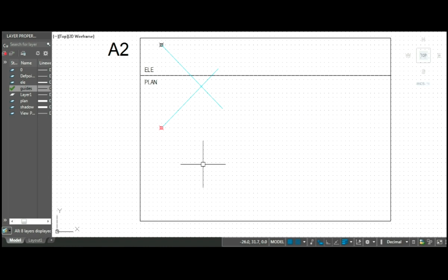The line that cuts the ground line first, or at the shortest distance, we draw a line perpendicular to the ground line downwards from there, such that it cuts the other 45-degree light ray. Okay, so the point where the vertical line meets the 45-degree light ray is the point where the shadow is seen.